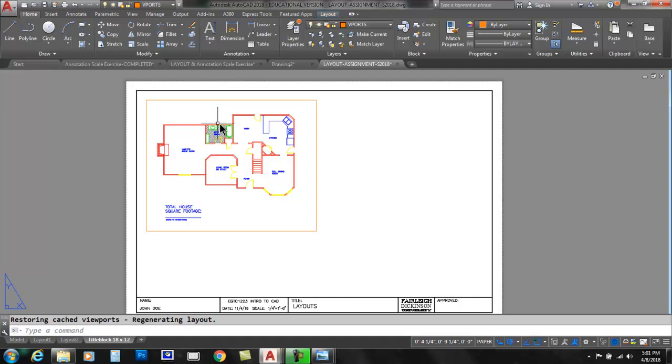You have to freeze the layer of the plumbing. If you simply shut it off, you'll still see the hatch will show you the footprint of it. I'm going to have to create another layer for hatch that'll blanket the whole room with my plumbing layer frozen. Then in my bathroom, I want to see it like it looks right now. Alright, I'm giving away too much here. You got to think about this a little bit.